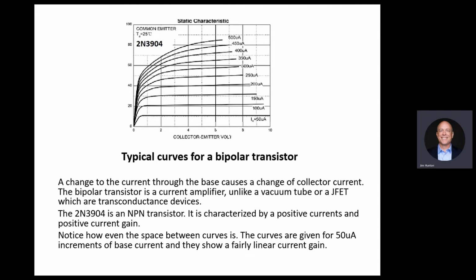And if you are counting on resistance and capacitance in the path, you need to take that into consideration. The device itself, any of those devices, is a real life device. It's not what the spec says. If you read this chart, you think that's the device. No, it can move because of deviations in manufacturing. And you have to account for those. And in some cases, it will shift your frequency response.